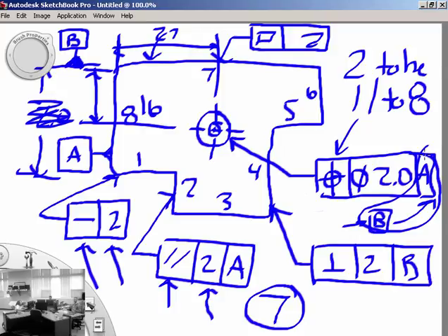Would they ever put both datums in there? They would probably put both, because a hole has to be located horizontally and vertically from some place. So if they're going to do one, they're going to do both. They may even do three if there was a depth issue, where they're afraid the hole would be drilled sideways on its way down. That's a possibility too. Definitely two if they're going to show it though. Questions on this? Alright, so it can be pretty straightforward.